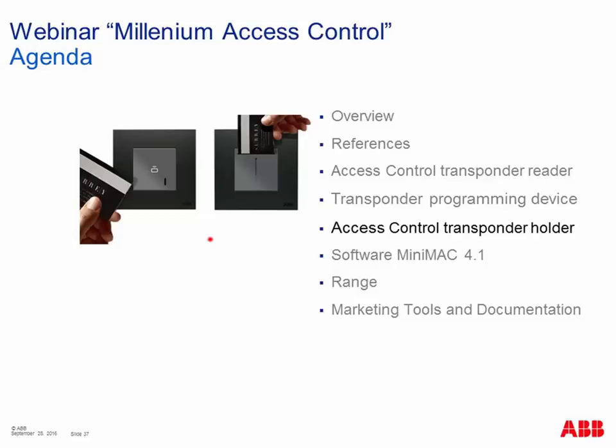This is the complete solution with our card holder, so the MIFARE card holder. Remember that in projects where you have cost saving from the building contractor or so on, you can use inside the room, instead of the card holder from access control, the conventional card holder. It is exactly what we have described in the slide before, and in this case the conventional card holder is connected to the installation thanks to the binary input we have on the card reader, on the transponder reader.